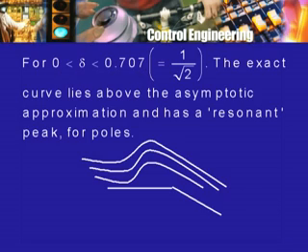In that case, the actual curve does not lie below this, but goes above this. So, it may, for example, have a shape something like this, and as you decrease the value of delta, that is, you make the system less and less damped, there is a higher and higher peaking effect taking place near this corner frequency.